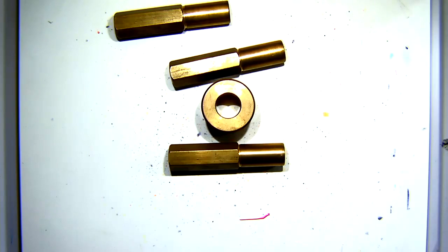So in that one, with standard shaft sizes, we would be going with a shaft basis fit, and in John's factory, the hole is that which has to accommodate. You can't have a hole basis and a shaft basis, it's not going to work, unless you want right on that edge of transition.